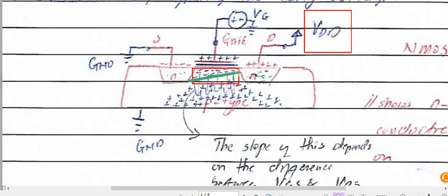So when Vg stays constant and VDS increases, as VDS increases to be more than Vg minus VTN, this thing will close up completely, and there won't be any electrons flowing. If I have to repeat what I said, Vg should be VTN more than VDS for this channel to be open. But when Vg minus VTN is less than VDS, this thing is going to be completely closed.